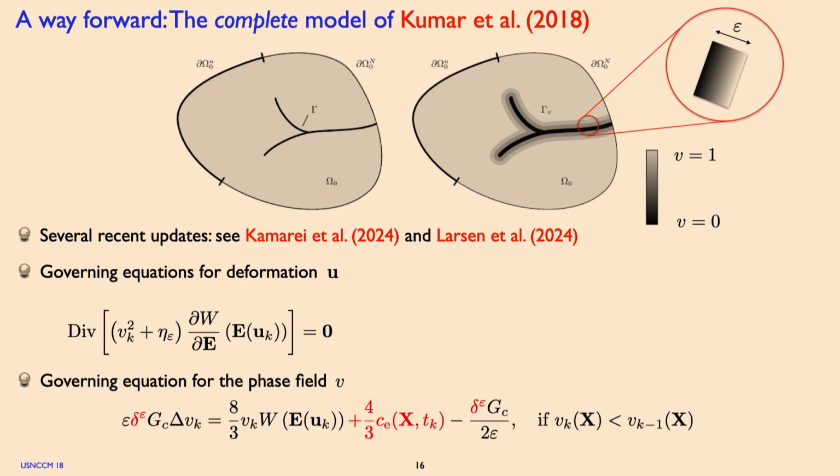Because what it's doing is it's bringing into the picture what was missing in these models. It's bringing in an additive way an external microforce whose job is to enforce under uniform states of stress that you have nucleation when you reach the strength surface of the material. Okay, whatever it looks like, it's constitutive information, right? It's an input to this model, okay? And this delta epsilon here is a rescaling so that you still have Griffith energetics dominating for sufficiently large cracks, right? So it has all three ingredients, and it's built in a way that allows you to recover these observations.